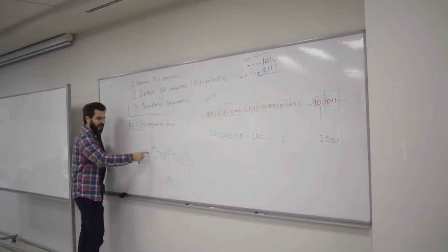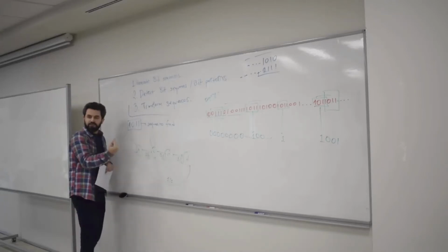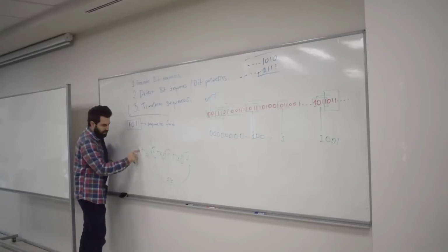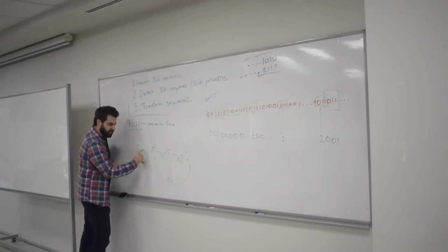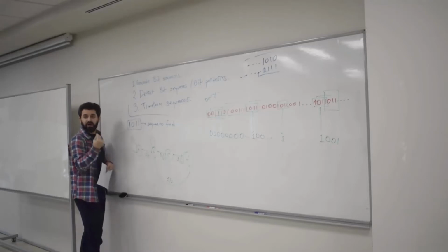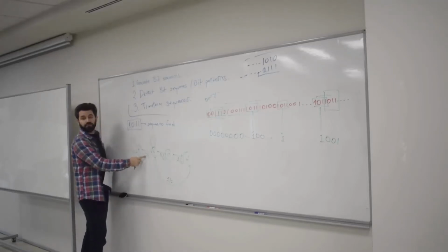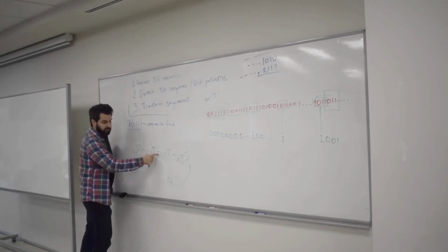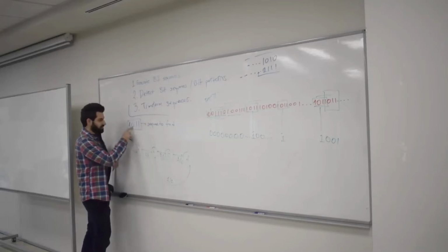Why? Because that 1 that you're seeing might be the first one of this pattern. That's why you don't need to go back, because this transition represents the following physical phenomenon. It basically tells you that the first 1 has arrived. Okay? Then, when you're here and you don't see a 0, okay, that's the second bit of your pattern.